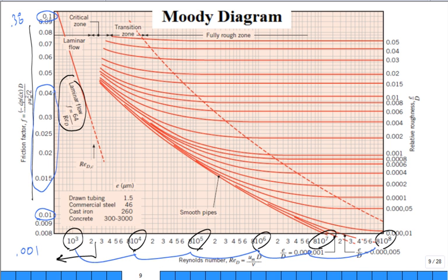Okay. Now let's take a look. What happens when you're done with the laminar flow? You have to somehow transition to turbulent flow. Do these lines nicely connect? No. They leave it to your imagination. Will they actually be connected? Yeah, they will, but it's hard to say with experimental clarity that that's how the curve transitions, because what do we have for all these red curves? What are they changing? The relative roughness. Relative roughness varies and goes up.